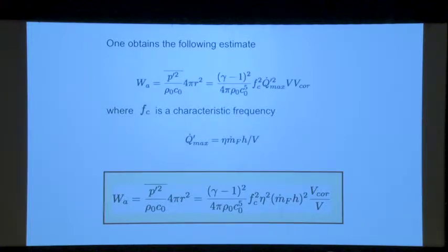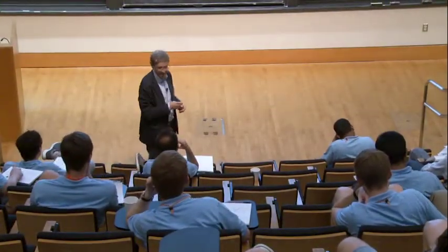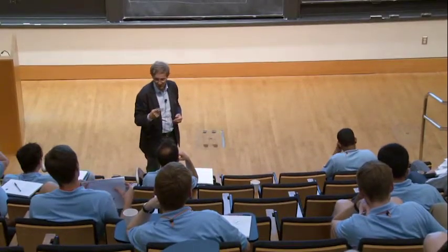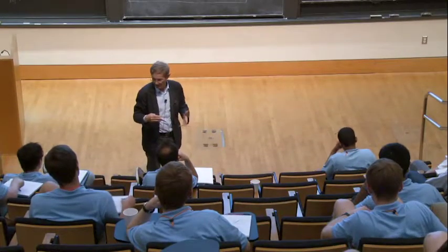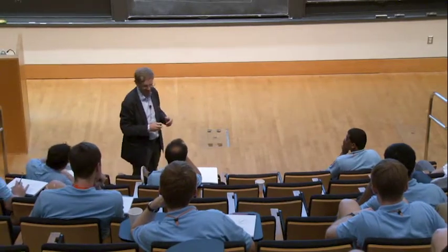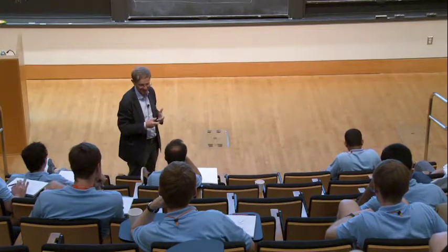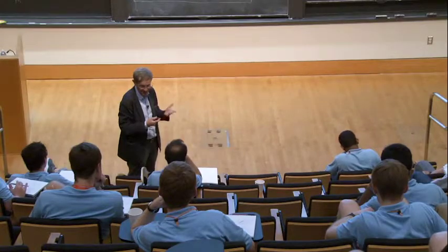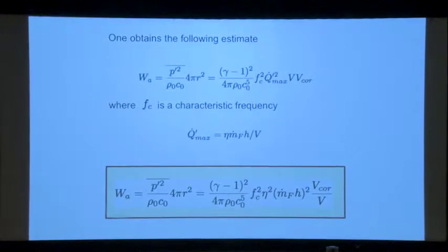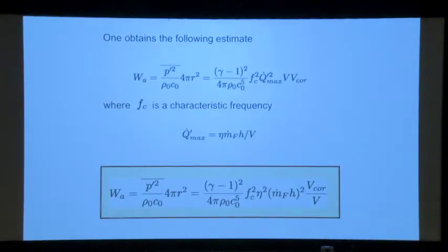And this is the heat release per unit mass. Typically for propane, it's 42 megajoules per kilogram. And for hydrogen, how much? One kilogram of hydrogen, how many megajoules does it produce? It's very important. It's 120. So hydrogen per unit mass gives 120 megajoules in terms of heat release. So here you have an expression that gives you the scaling of this. We will see how that comes out in plots.